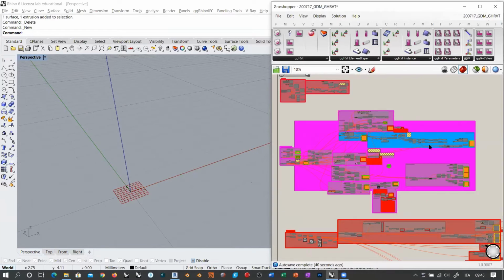like for example in this case, I'm not doing it because this could also hang Grasshopper, the IFC encoding here and the implementation of this workflow, which creates several things like columns, beams, floors, walls, truss systems, and many things, will read the information in this document in millimeters. So basically, the model will be scaled up like in a huge preview. And this can also hang Grasshopper because of the graphic card capabilities.